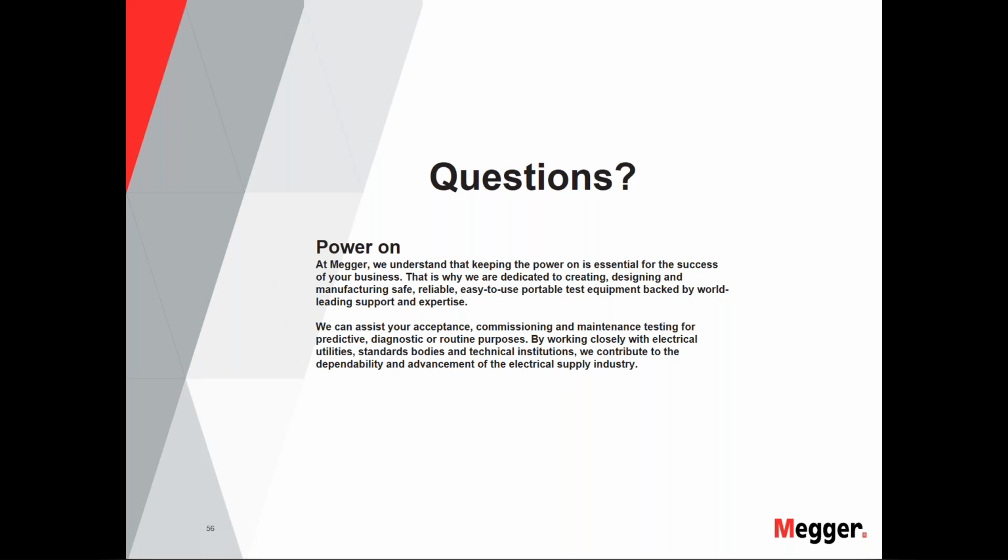One is during pre-commissioning, like the SAT test, where you can verify it, or just inject the voltage, not in the SAT test. Just inject the voltage from the HV side of the GSU, like your 3-phase supply, and short circuit the secondary. It may be very little current generated based on the reactance impedance of the generator and the stator circuits, but still you can see the current flowing into the circuit and check the CT polarities.